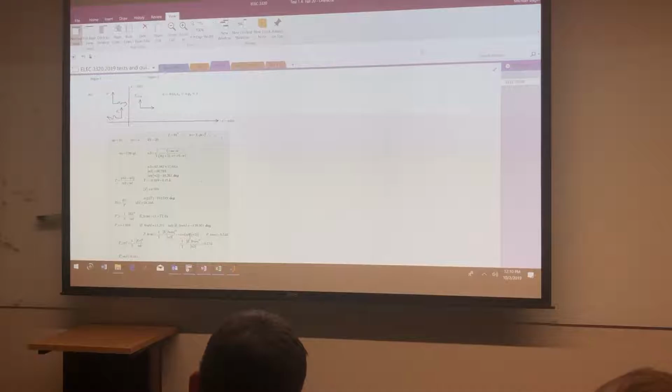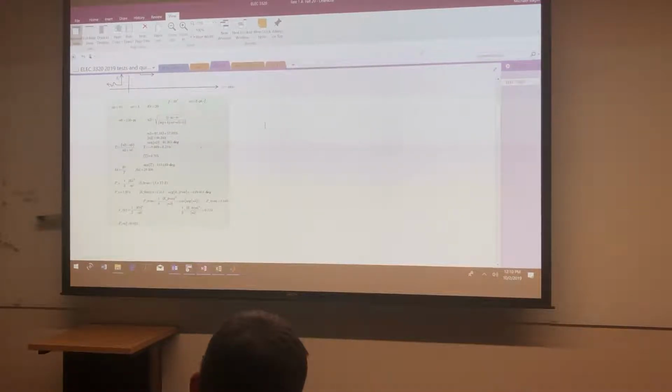After that, coming down here, what else? The reflected power. Here you don't have a cosine because the angle for eta naught is 0. So it's 1/2 E reflected field squared divided by eta naught. And that's the P reflected.